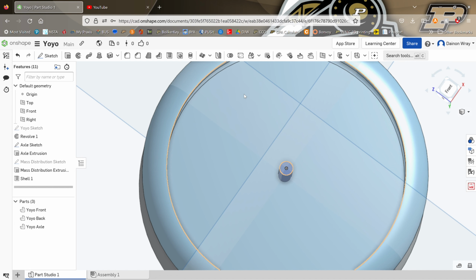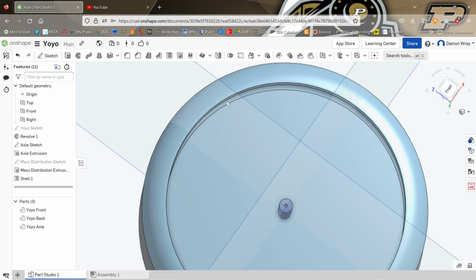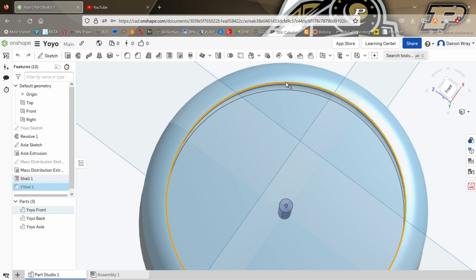Now I want to show you how to smooth some of the edges. Now, fillet and chamfer are very, very good for creating a finished product or something that is ergonomic and takes away the sharp edges. It's often like sandpaper, but I call it digital sandpaper. So in order to fillet, this image explains what it does. It curves over the edge. So we're going to do that for our first edge that we just shelled.